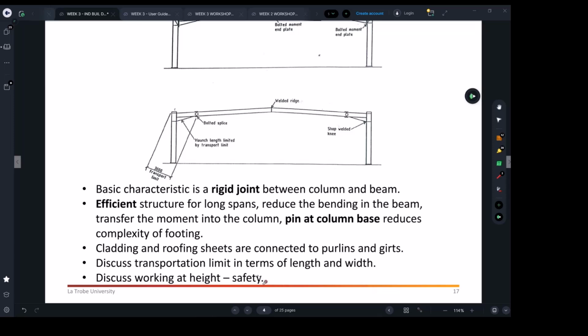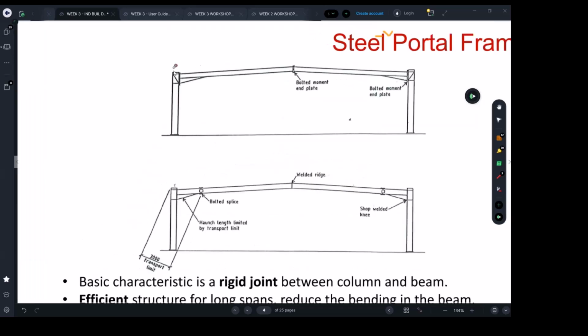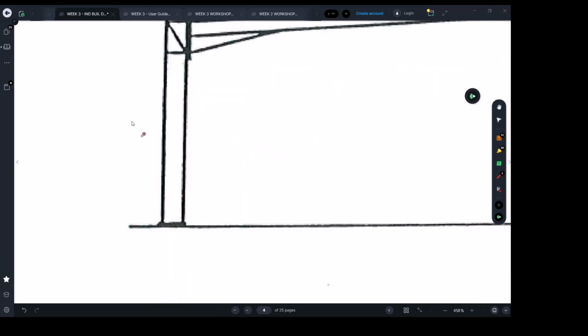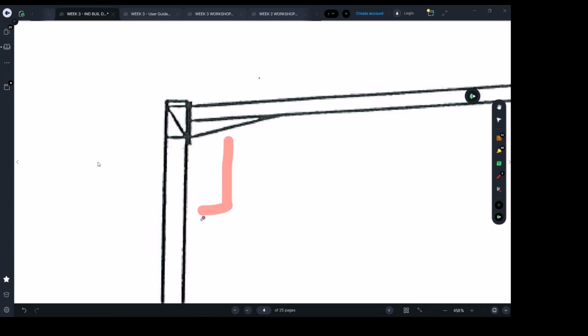Okay, so basically, as I was saying to you, to avoid having contractors work at high level, to make it workable, if you think about having contractors do all the welding on site, you need to make sure the safety considerations are all met. You're going to be putting scaffolding around each column, with the height issues and the fencing issues.